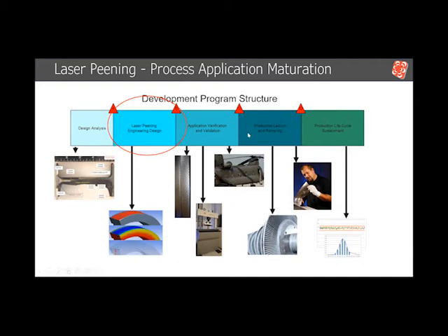And then the production launch: once you have developed that process condition, you lock down that process so that you can use that same processing condition and pattern over and over again, and you have verified it with your previous effort to validate it. And then it's supporting the production so that you can purchase the process on the parts, and the customer who ultimately receives the laser peened component realizes they're going to have the same benefit in the part.